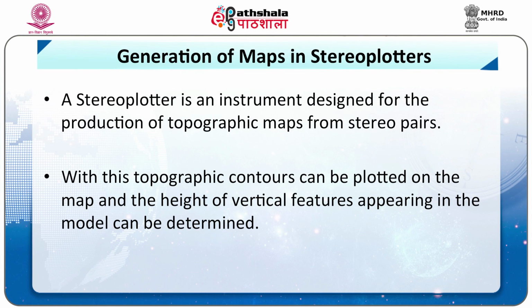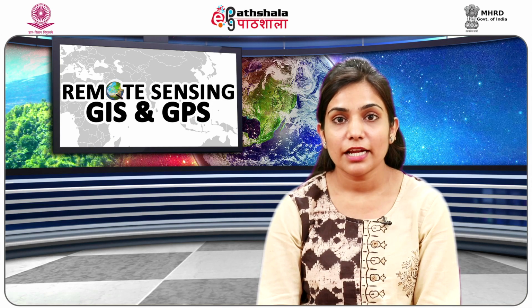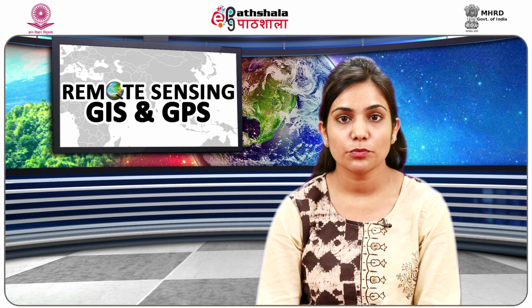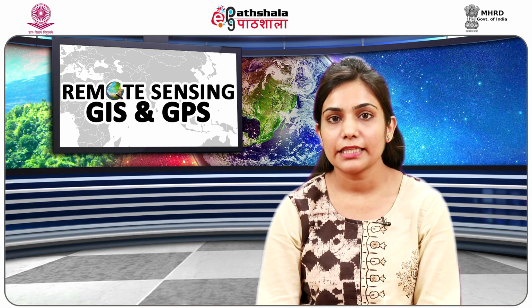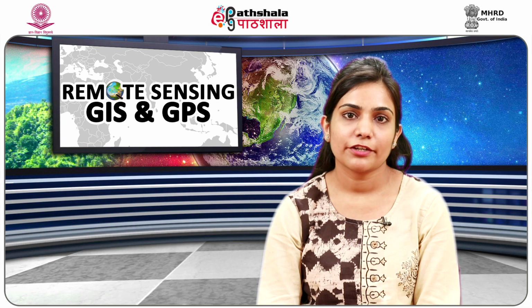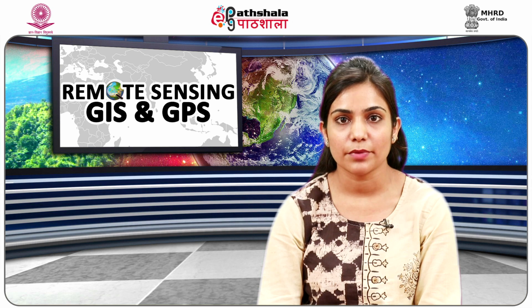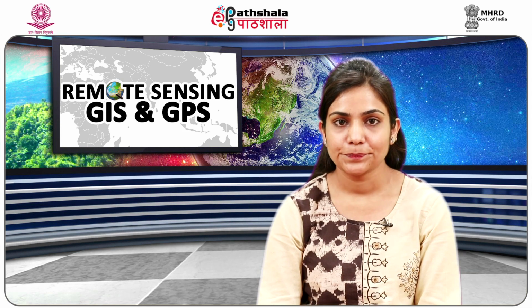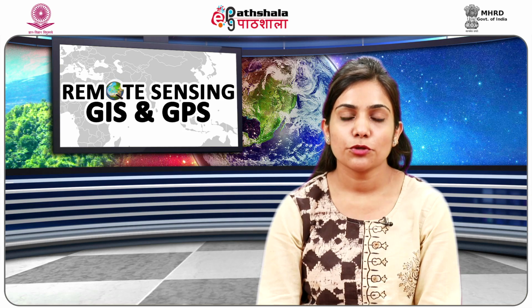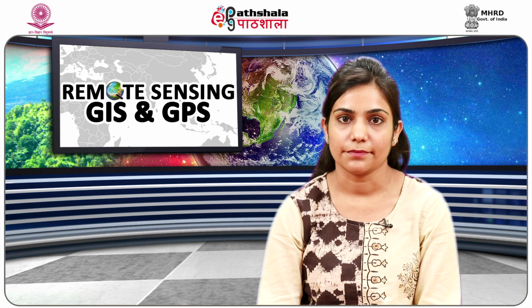With this, topographic contours can be plotted on a map and the height of a vertical feature appearing in the model can be determined. With the advent of technologies, stereoplotters have changed, starting from projection stereoplotter to Kelsh stereoplotter to analytical stereoplotter. Analytical stereoplotter is now being used for different analysis. It incorporates a computer which does the work of mathematically aligning the images so that they line up properly. The analytical stereoplotter also allows for storing the data and redrawing at any desirable scale.